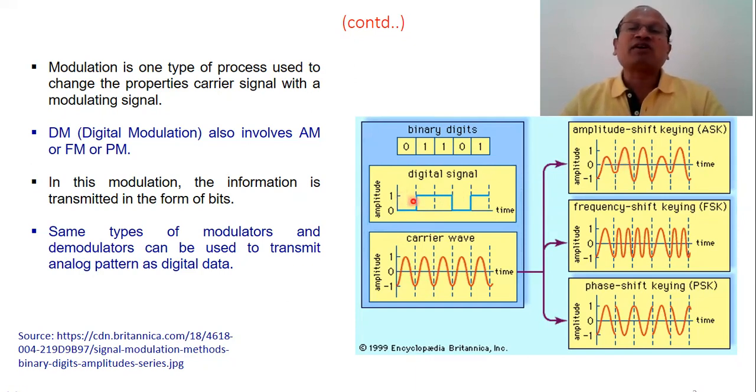Whenever the bit values are low, the amplitude becomes low, and so on. So this can be continued for the continued expression of the waveform of the carrier signal. What we can observe in ASK is that it's similar to amplitude modulation, but not analog. It's digital, because the data, the message here, is a digital signal. The carrier, of course, is an analog signal.